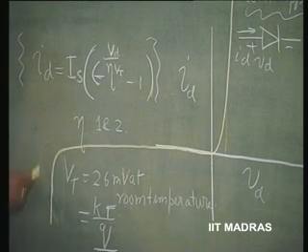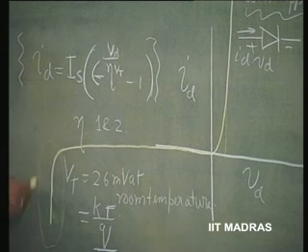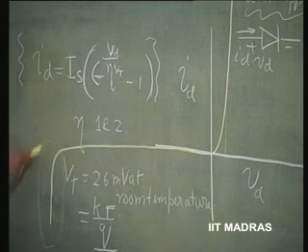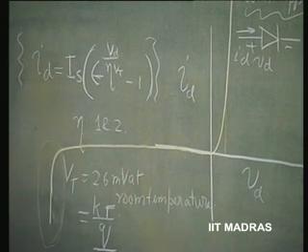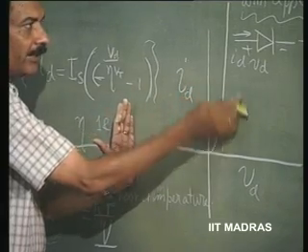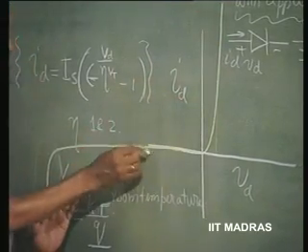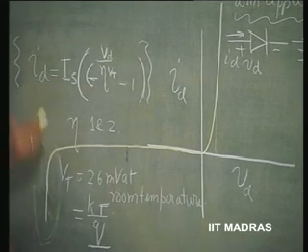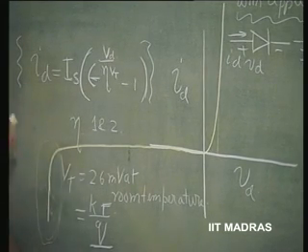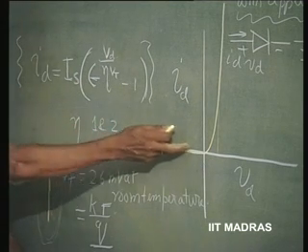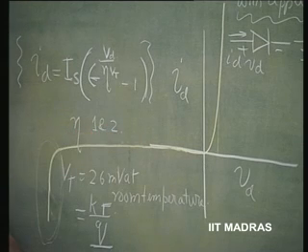This region is called a Zener diode. Breakdown may be formed by what is called an avalanche phenomenon or Zener phenomenon, but these diodes which are used in this region are called Zener diodes. The rectifier diode is primarily used in the forward biased and reverse biased region where it does not break down. Earlier we have mentioned that for our rectifier diode, the peak inverse voltage rating should be such that the diode never breaks down. Diode is always in this operating region.